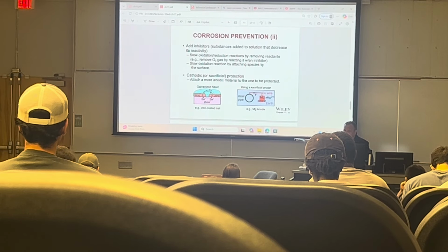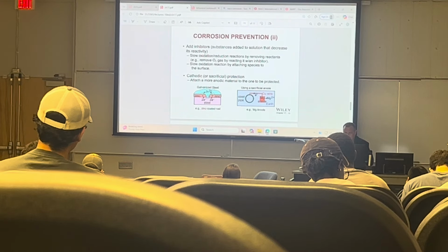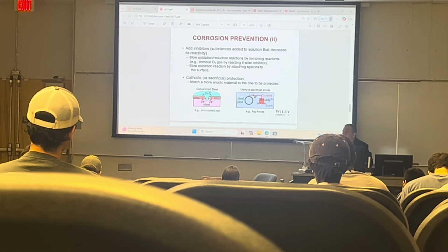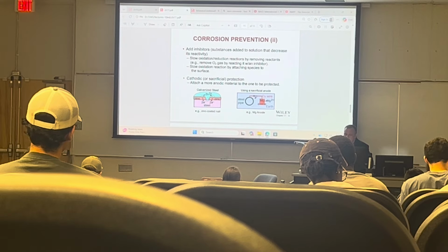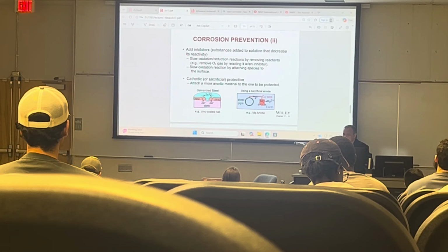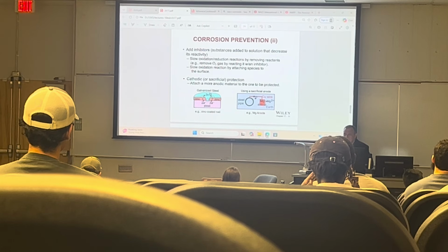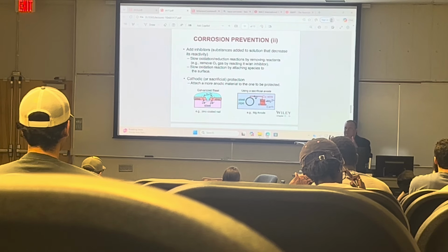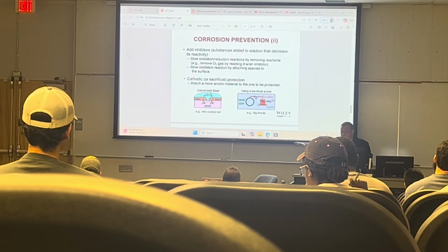And finally, there's sacrificial or cathodic protection. If you add zinc on steel, zinc is going to decay first. The other option is to put a sacrificial anode. And that's exactly what they've done on those balconies. The problem is, once you place this material inside the concrete, they did not put them low enough. So once this thing deteriorates, because it's expandable, you end up with a hole. So you have to be careful how you do it.